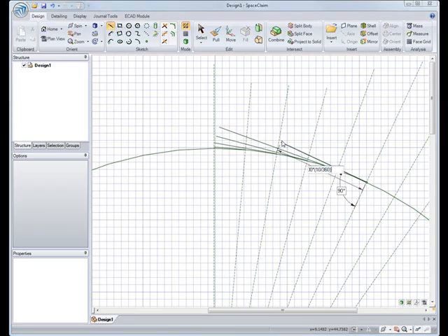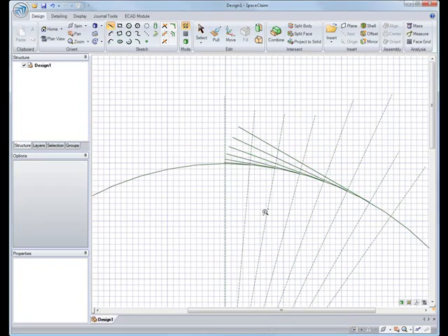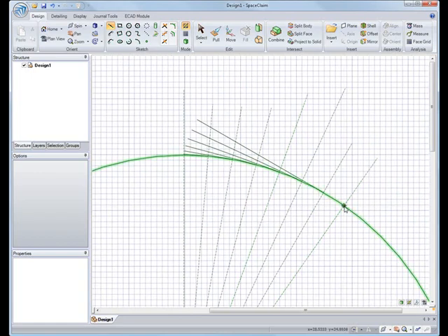You might even want to go back in and change the spline a little bit more. Maybe create them 5 apart to start off with. And if you feel that you should have a stricter tolerance, you can start adding them between them, maybe 2.5, maybe 1 or 2 degrees. So we'll change this to 30, and then put in one more. This is definitely the slow way to create an involute, but I'm still getting it done in SpaceClaim.